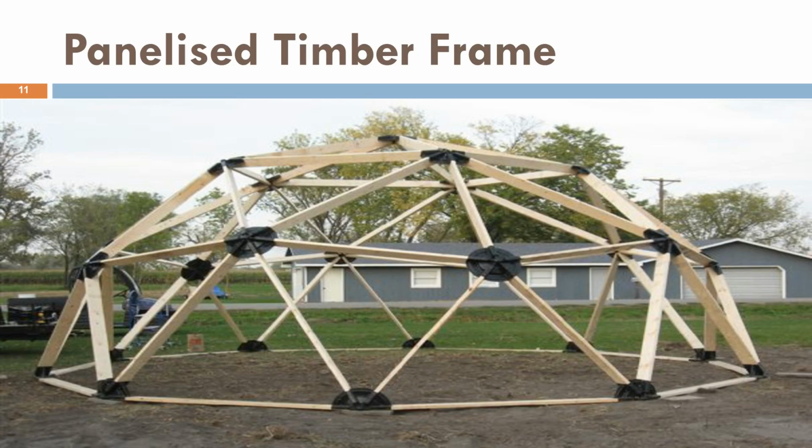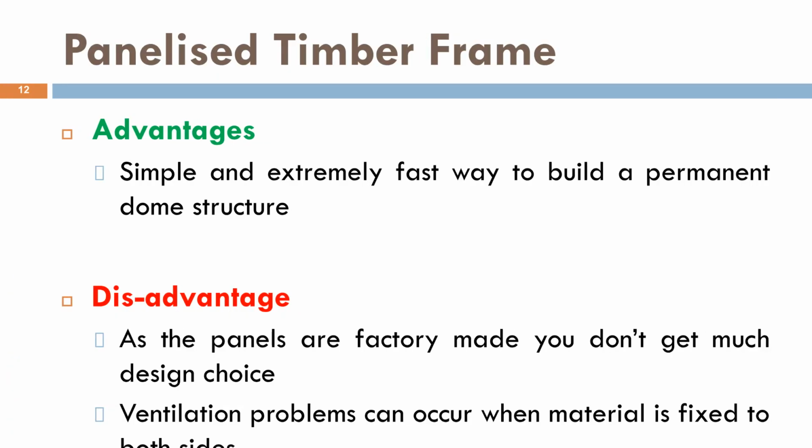A panelized timber frame uses prefabricated sections to create the dome structure. The panelized timber frame method uses factory-made timber panels that are assembled at the construction site. This method is very fast and suitable for permanent dome structures. Since the panels are prefabricated, construction quality is generally good. However, there is limited flexibility for changing the design. Also, fixing materials on both sides of the panels may reduce ventilation and create moisture-related problems inside the structure.